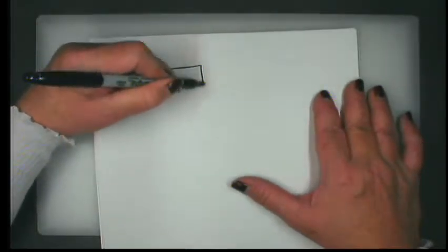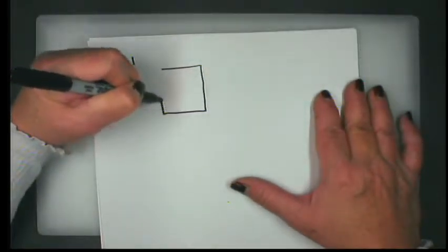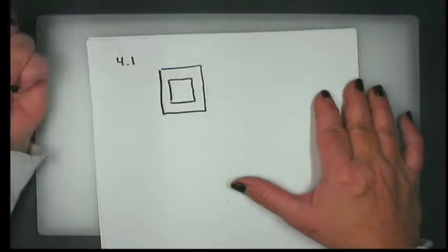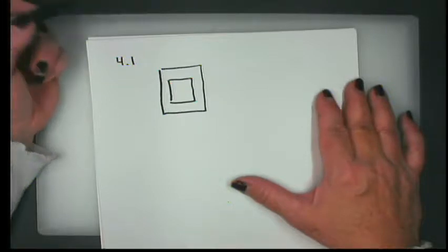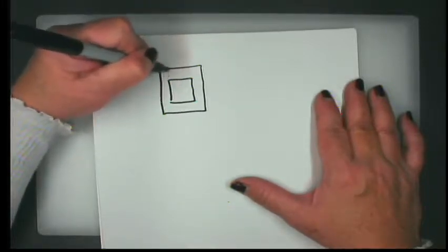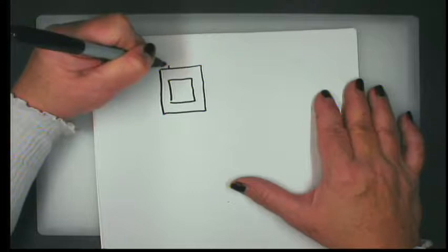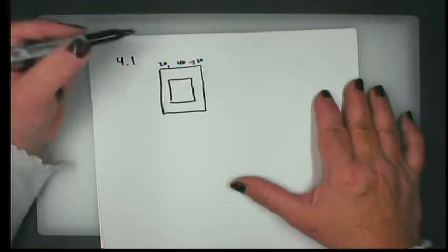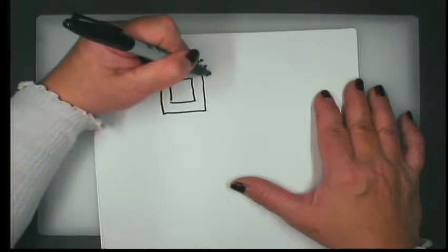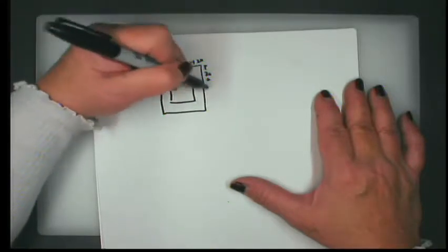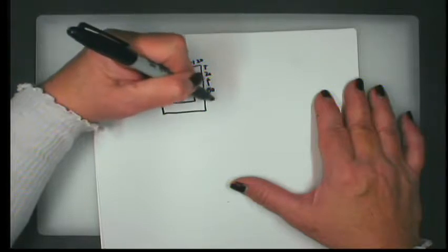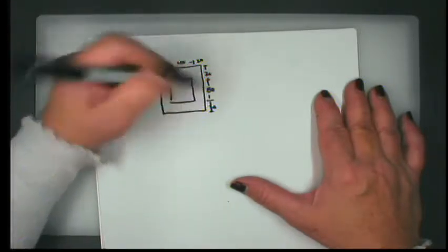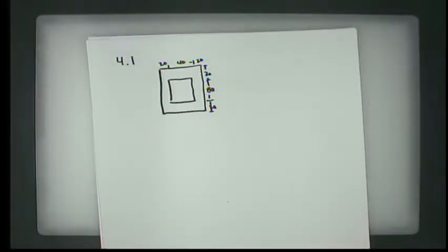And we are drawing a cross-section that is a hollowed out rectangle. And we're given dimensions in millimeters. We're told that from here to here is 20 millimeters, from here to here is 40 millimeters, and 20 here, so we have lots of symmetry. On these types of problems, at this stage of the game, we have to have lots of symmetry, or we're not able to do the math, because moments of inertia are integrals.